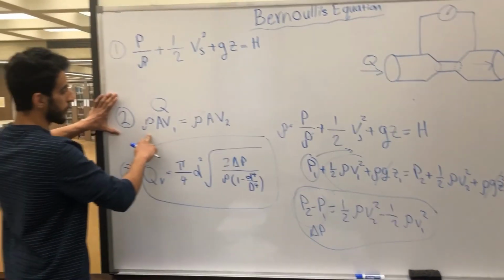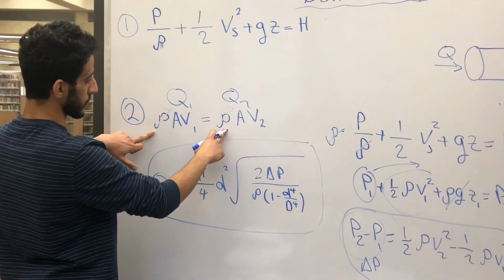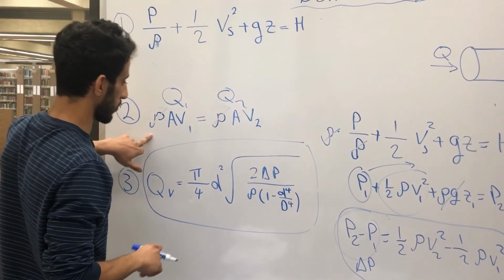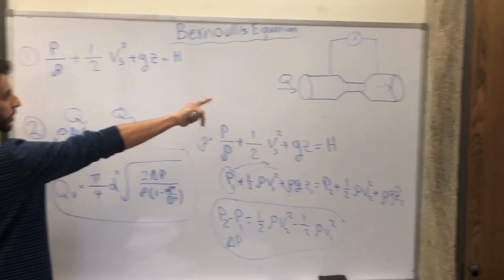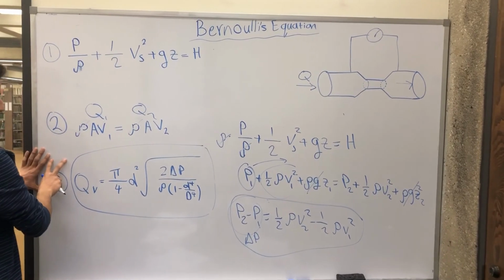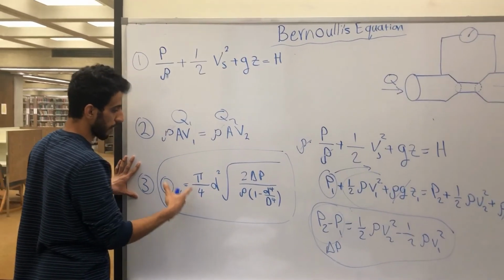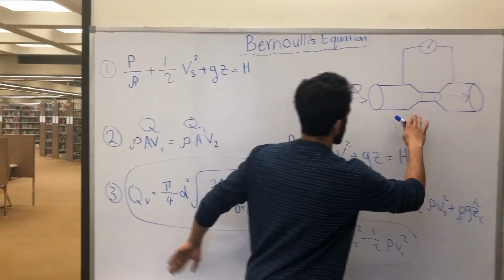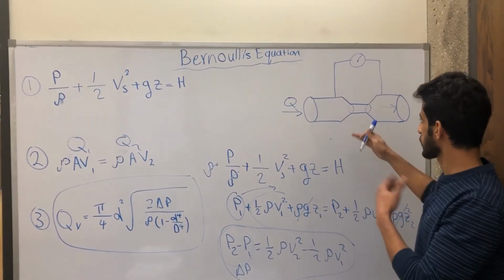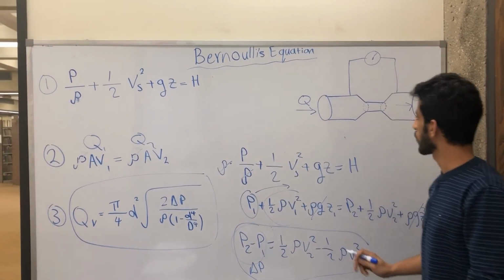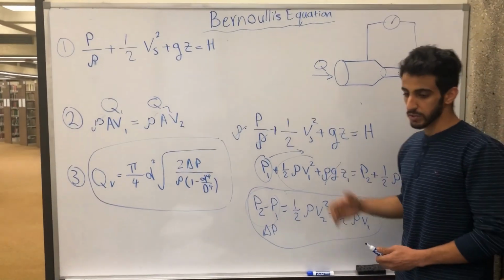Right here we have the flow rate, where big Q1 equals big Q2. The density cancels out, as we said, because we work in an incompressible situation. And maybe the picture there will help show where the cone is and how it works. This works more accurately for the flow rate by adding the area, because as you see in the pictures, you might have a difference in diameter, so you will be using this for flow to get more accurate results. That's it for Bernoulli's equation and how it applies to our topic.